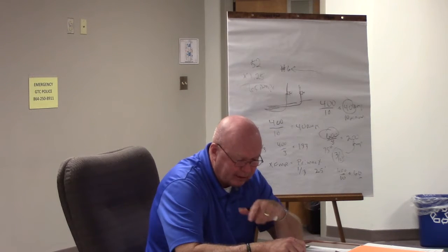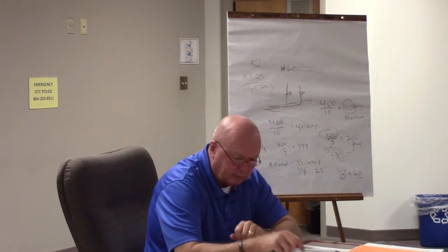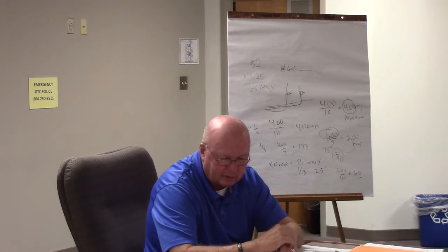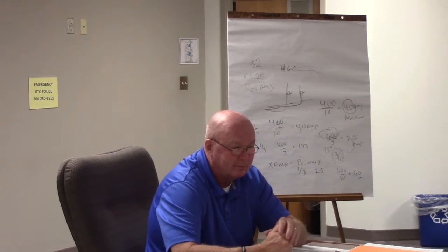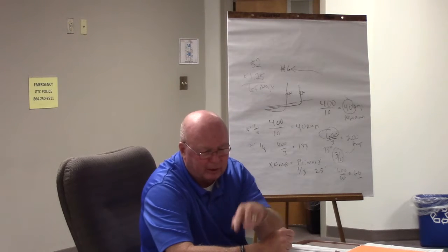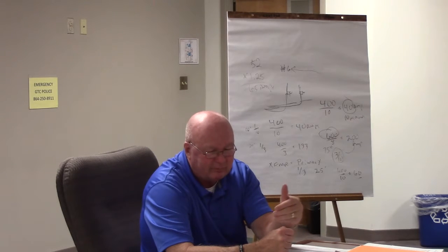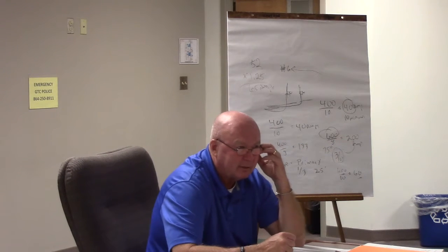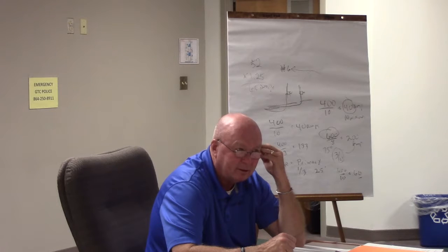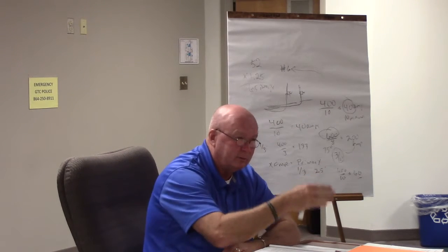220.44 just talks about receptacle loads other than dwelling. And you see what the rule is there. In 220.54, we look at clothes dryers. The biggest thing I want you to know about clothes dryers: if you've got more than 4 clothes dryers in your house, you've got a big family. But this would apply when we have apartments. 1 to 4 is 100%. When you get over 4 to 5, then you start to derate. This is because in every apartment you have a dryer connection, right? Pretty much. Hopefully you do, unless you really live in the slums. That rule may come into play when you've got multiple dryers on one service.